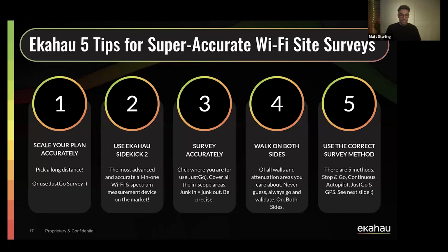So it's really important that you capture the data accurately and collect the data on both sides of the things that you care about. So if you want to know how much attenuation a wall is going to cause you, walk on both sides of it.